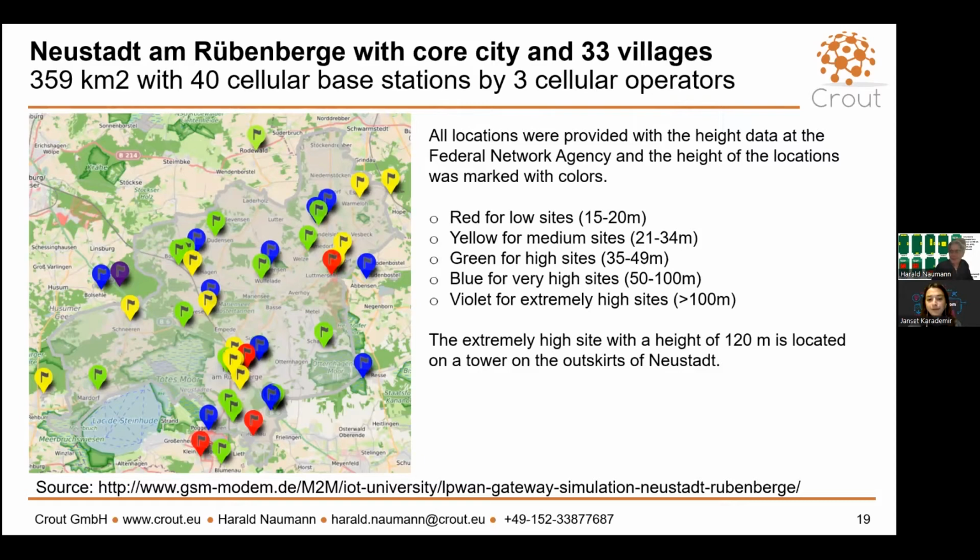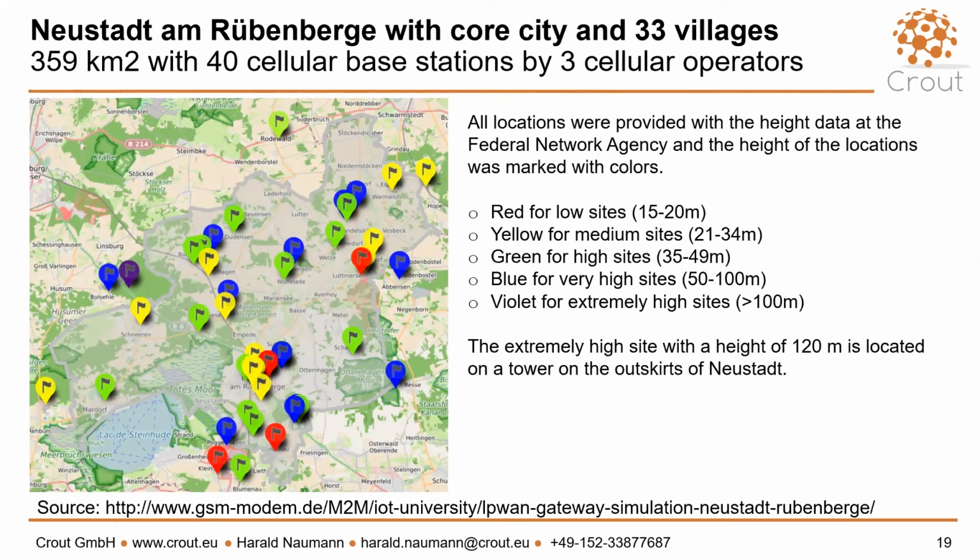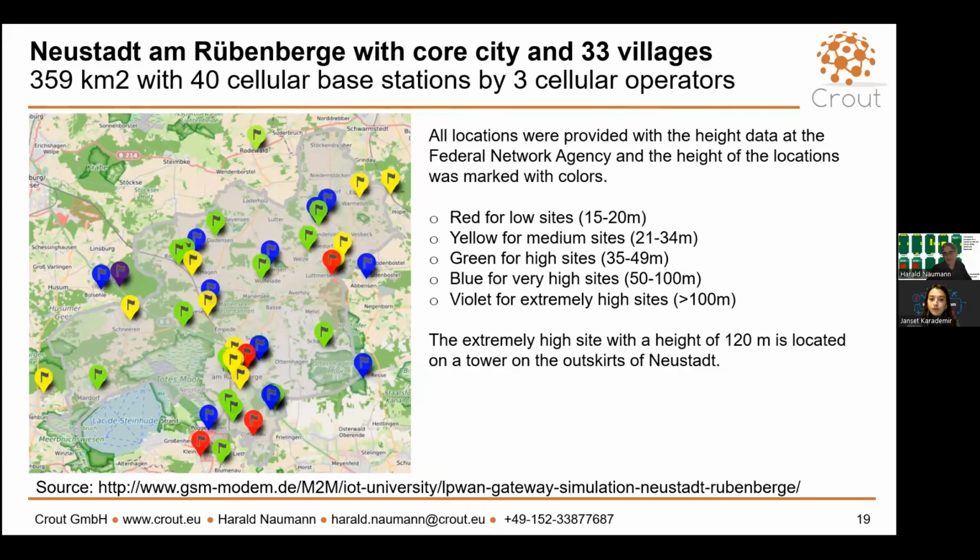And the other question was, what are the typical effective data rates and latencies with LoRaWAN? With spreading factor 12, that means the highest link budget, we talk about 297 bits per second, so an estimated 300, but that is gross, and if you calculate net, then it's already lower. So it's ultra slow. And if you are limited to 1%, that means you can send, and then you have to wait a long time before you are allowed to send the next time.